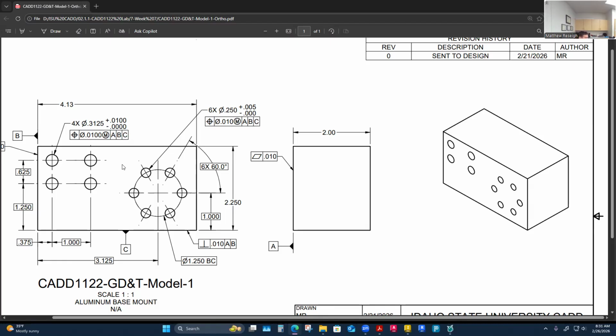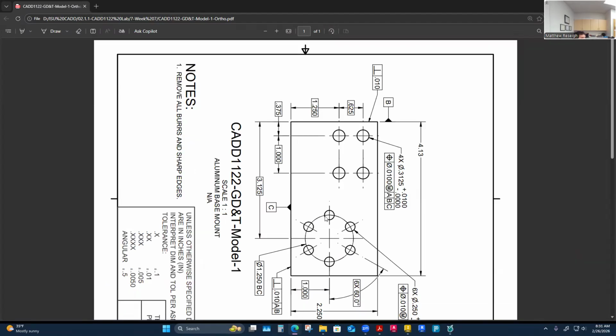If they're level, you're two-hole and you lock it down and tack it down or weld it up or whatever. And it's a little harder to get something leveled and straight if they're going to put a hole on the top, especially when the part lives like this, where this is how it's sitting. And obviously if I flipped this thing this way, this would be a single hole. And this is kind of hard for a fabricator to install and get leveled out, making sure that it's not slightly tipped one way or the other.